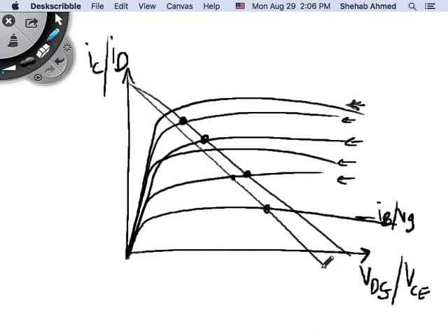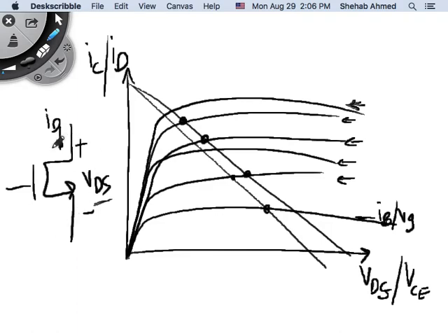Again, this is 325 material. You don't have to remember it, but think of it this way: you have a device. I will draw the device here, for example, with plus minus VDS, and this is the current ID, the current through the device and the voltage across the device. I can choose the voltage of the device to be here, here, here, based on my operating point. I was putting some resistors around the device and making sure that I'm biasing the device in the DC operating point in a certain way to be able to choose my DC operating point, and then you were doing the AC operating point analysis.